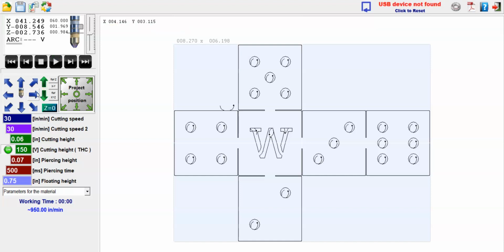On the opposite end of the spectrum, let's say you did want to move around slowly and wanted to get those micro adjustments, those fine adjustments to get the torch exactly where you want it to be. The way you would do that is by holding the control button and hitting the left button, and you'll notice by holding the control, the actual x-axis is moving much slower than it would without it on here. So that's normal function. This is simulated with speed here, and then again we have that shift to increase the speed, make it go faster here, control to make it go slower, and this is for any motion across the table.